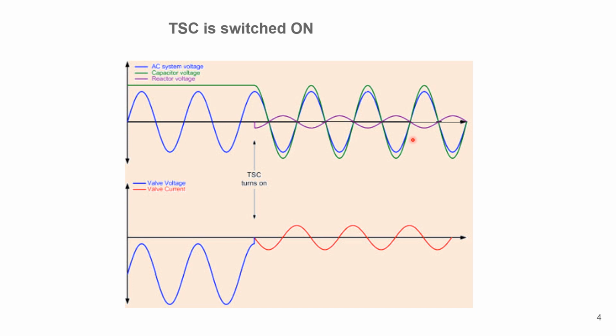You should take care of the analysis of current transients after closing the switch. There are two cases. When the thyristor-switched capacitor is on, the inductor and capacitor form a resonant circuit, so oscillatory current flows.